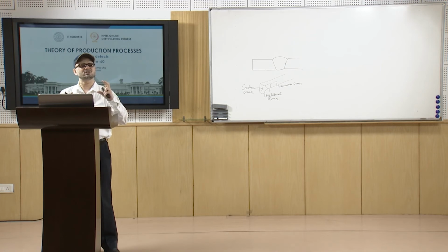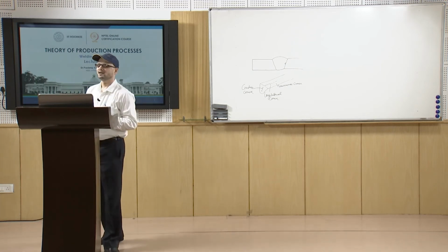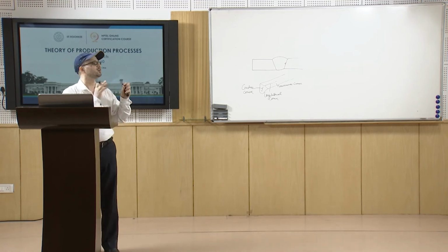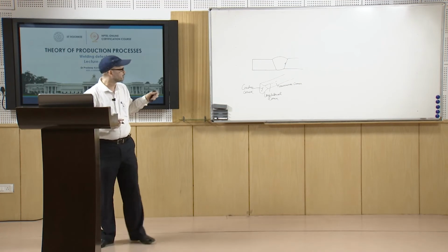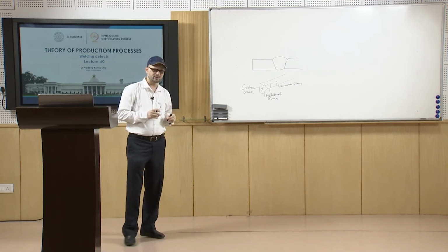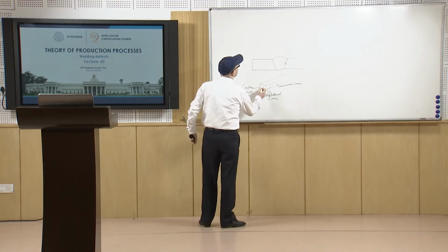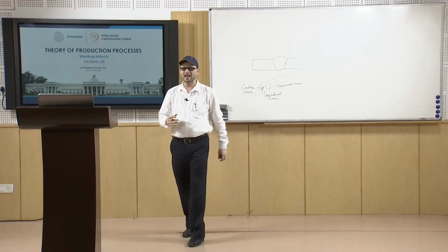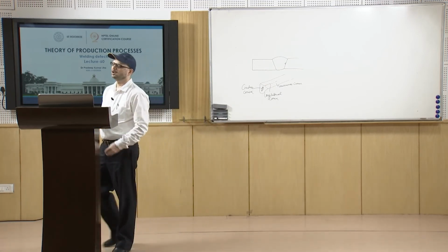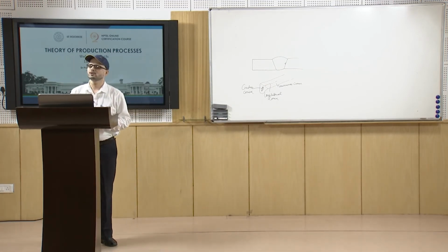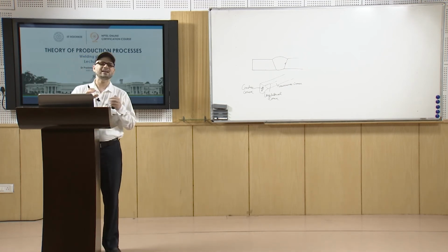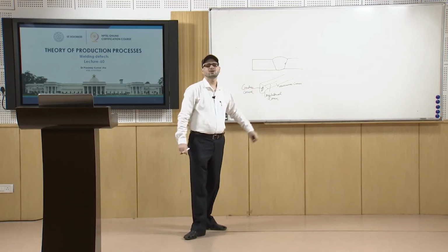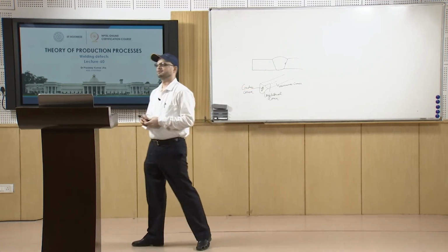Now, discussing the crater cracks, they are basically caused whenever the welding operation is interrupted. Once you are doing the welding operation and you interrupt in between, many a times the crack comes and further aggravates as the weld cools. So, what we do is many a times we fill these cracks so that the crack does not propagate in the case of crater cracks.